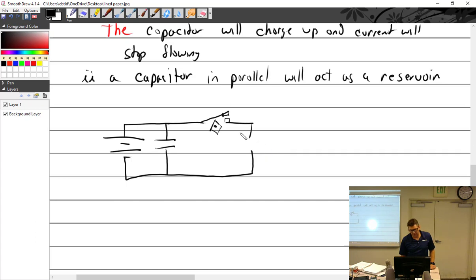And there's some other stuff going on that we'll get into when we get into magnetos. But this is no longer a battery. We'll say it's a very large AC source. And so we have a rather large source of electricity right here, and it's going to go off onto some coils, more or less. And what you end up getting is a pretty large current going through this, or I should say voltage. It's a very high voltage. And so a high voltage can jump a gap.